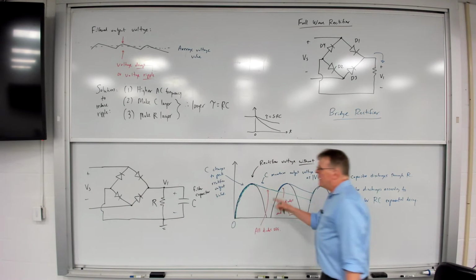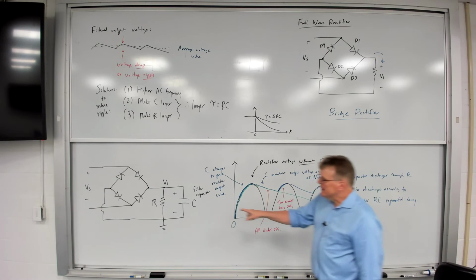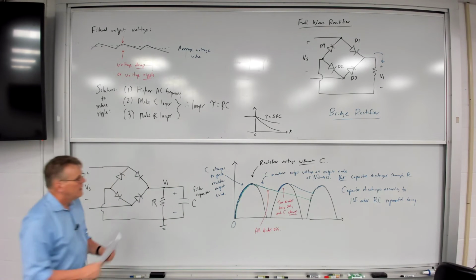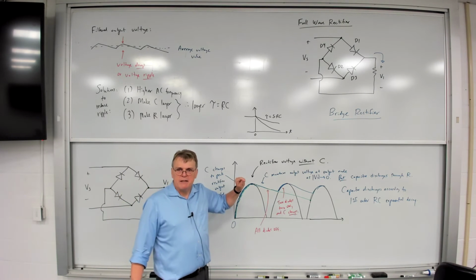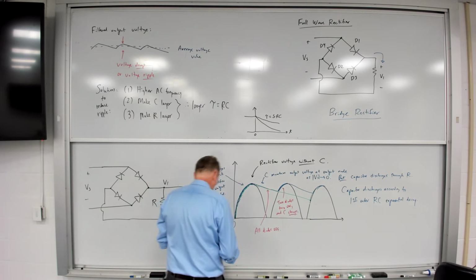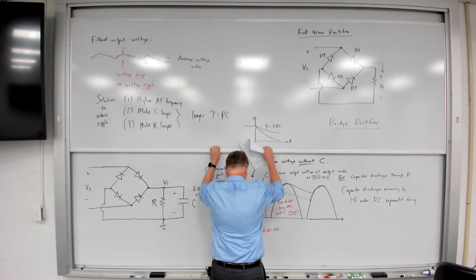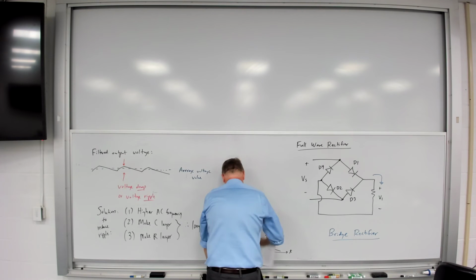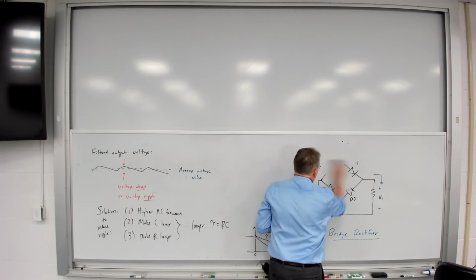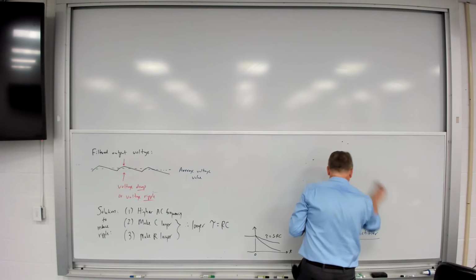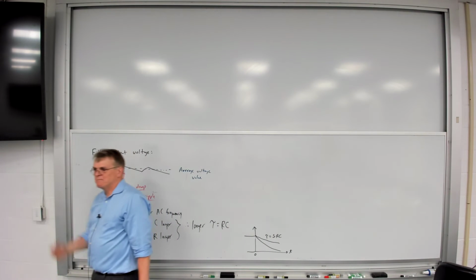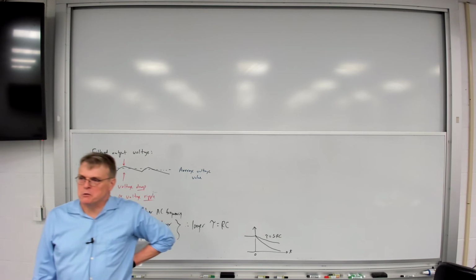So the full-wave rectifier works very well with the filter capacitor, and typically we will make that filter capacitor big, as I said before. But could we do better than this even? Could we somehow get rid of this ripple? Let's look at this. Remember we talked about voltage regulator circuits. And what did we say was one of the properties of voltage regulator circuits?